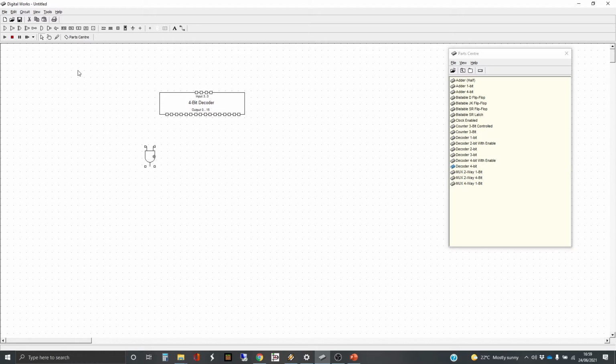So what am I going to do? I'm going to add a tag to this. I'm going to use copying and pasting to multiply this up. But that's going to be our first input. This says output from the decoder. So we're going to go 0 at the left to 15 at the right-hand end. The reason for sticking the tag on there is because I can neatly duplicate these.